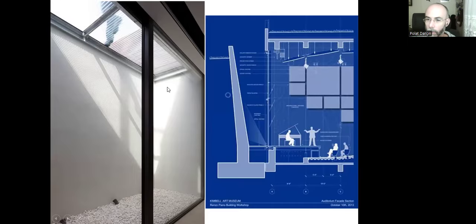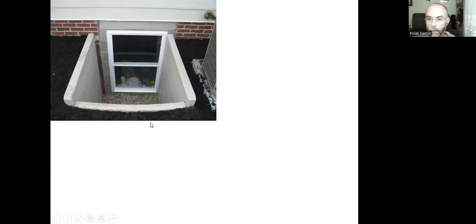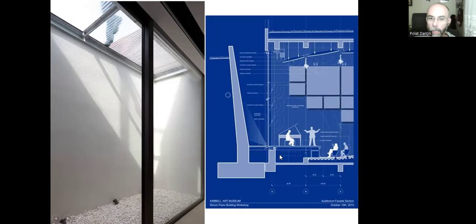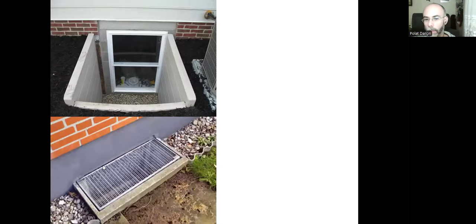But if we need both air and light, then we can have an open areaway so that the air can be circulated as well. But there is a risk for users to fall down if there are people walking around the building. So we can prefer closing it with a net or a grid like this. It will allow both the air and the sunlight.